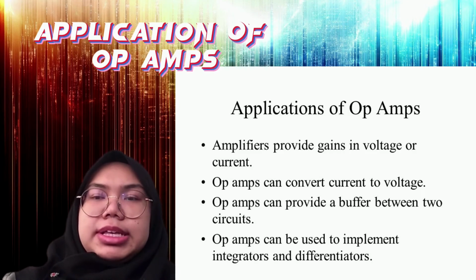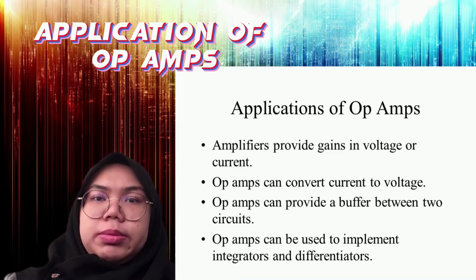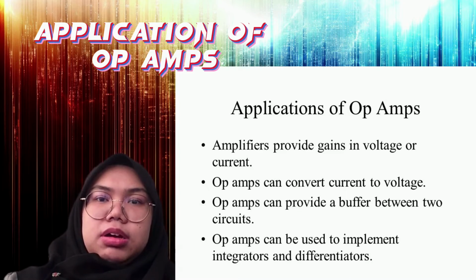An op amp is an IC that amplifies the difference in voltage between two inputs. Op amps can be used for various applications depending on the external components added. In the most basic circuit, op amps are used as voltage amplifiers, which can be broadly divided into non-inverting and inverting amplifiers. Voltage followers, also simply called buffers, are a type of commonly used non-inverting amplifier.